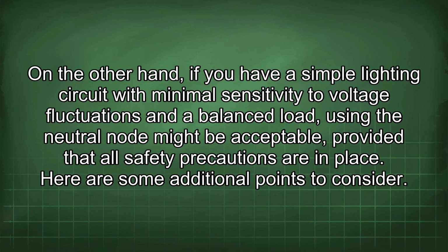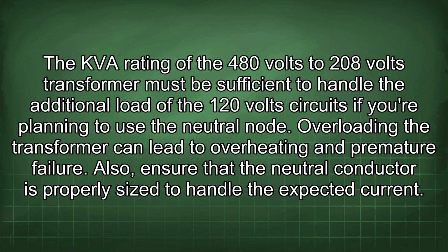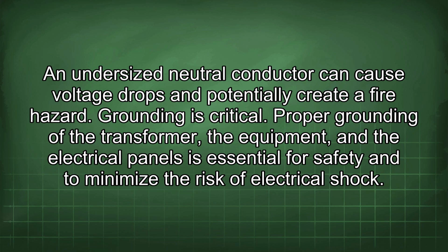Here are some additional points to consider. The kVA rating of the 480 volts to 208 volts transformer must be sufficient to handle the additional load of the 120 volt circuits if you are planning to use the neutral node. Overloading the transformer can lead to overheating and premature failure. Also ensure that the neutral conductor is properly sized to handle the expected current. An undersized neutral conductor can cause voltage drops and potentially create a fire hazard.